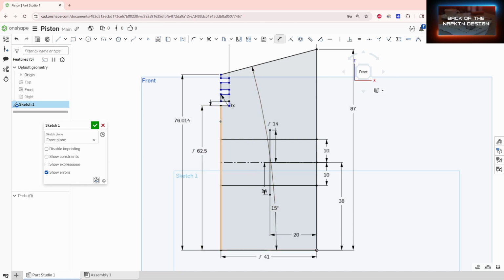Okay, so now we need to curve this up, and there's a wall here. Let's create that wall. So we're going to create a line here. It's going to be parallel with that, so we'll keep that. You'll see that in the lower right hand corner, you see parallel.